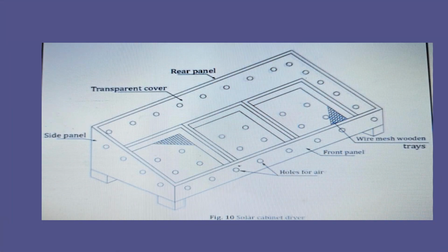But the drying time is sometimes more and the low efficiency of the dryer are the disadvantages of this dryer. Though it has improved drying time as compared to open sun drying, to some extent it is a disadvantage that the drying time is not as short as we can expect. The first solar cabinet dryer was fabricated and tested by Lawand at the Brace Research Institute with a loading of 7.2 kg per square meter of drying area.